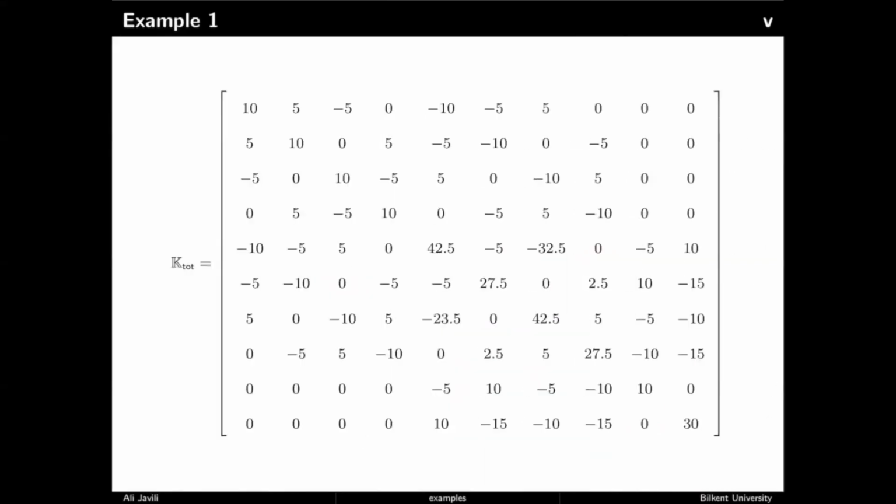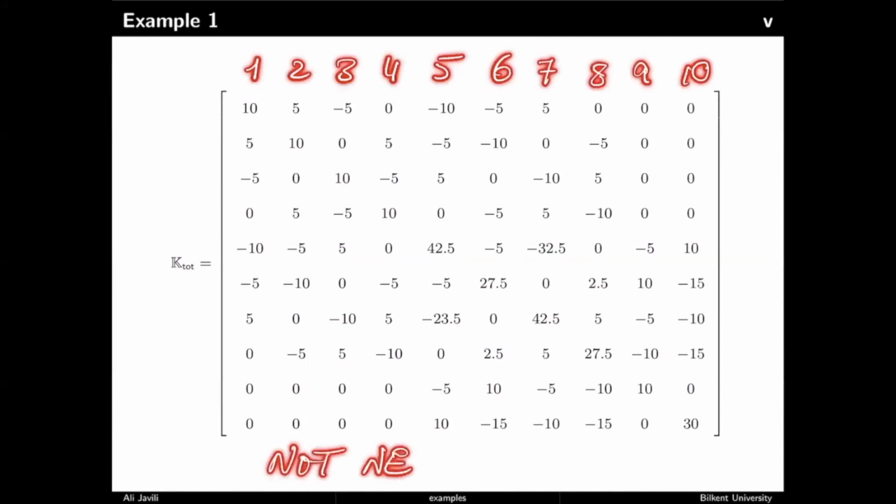All right, so if you assemble the two elements, now you would have this one, and these are those global numbers that we talked about. By the way, I have never asked you to calculate this. This is just for fun. The question does not ask you to assemble the global stiffness, and that would be a little unfair. That's too much work. That's a very large system. So you do each of those systems. The question actually asks you to calculate the reduced stiffness matrix.